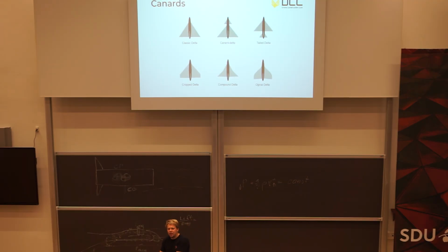In the back, it's going to be passively stable. In the front, now you're shifting the center of pressure weirdly, you can control for it, and that's why a lot of fighter jets are actually running canards, not pitch stable, instead of horizontal stabilizers in the back, because you can actually get more control authority out of them.